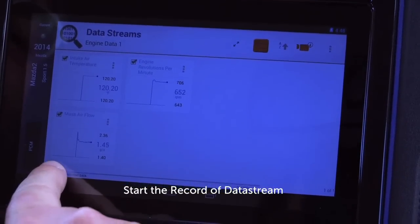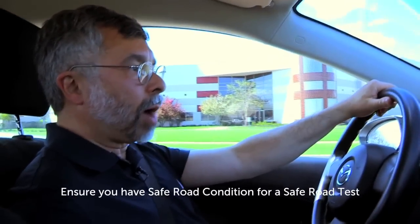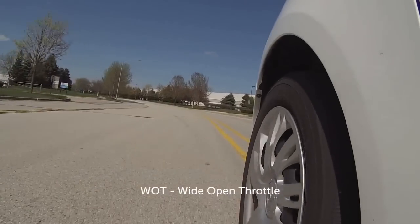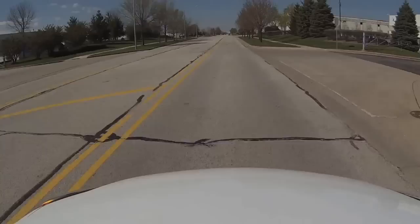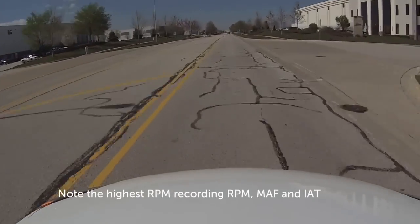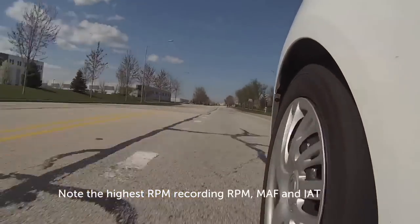Now I'm going to go ahead and start my road test, and from a cruise speed, I'm going to press the throttle all the way to the floor to wide open and then record the highest RPM and intake air temperature and mass airflow sensor readings at the same time. Now we've got to our highest RPM, we're going to go ahead and slow back down and we'll head back to the shop.